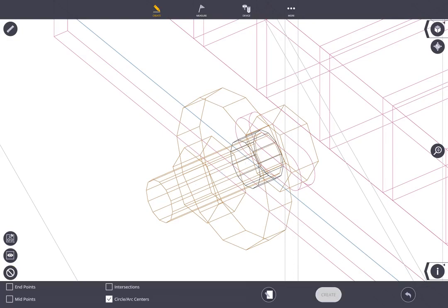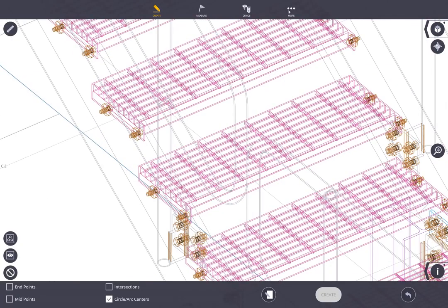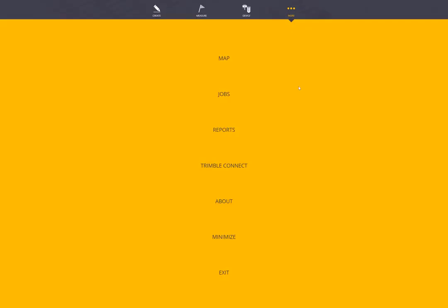We can also do this with the window selection tool and just grab the entire bolt pattern here. If I do that, you're going to see it creates 9 points along each of the center points where it's hitting the face of the bolts, the face of the item it's bolting to, the face of the nut, and the other end of the bolt here. So quite a few points along that area. Again, if you want to isolate just one of those items, we can do that as well. For now, I'm going to go ahead and not create those points, and I'm going to show you how we can double check with another model just to make sure that we're getting the points in the right location.